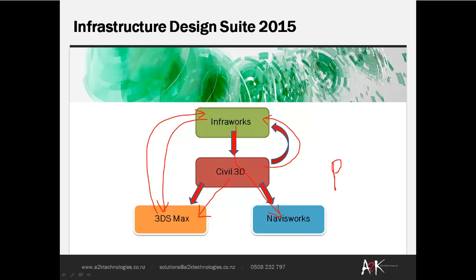You've also got Revit in the Infrastructure Design Suite sitting off to the side here. Civil 3D to Revit you can do with the Bridge Modeler, which we've done in previous webcasts, and also Revit can come back into Civil 3D. In fact, in what they call a building site, and there's a little function for that. It's not used very often, it's not needed very often, but it is possible.